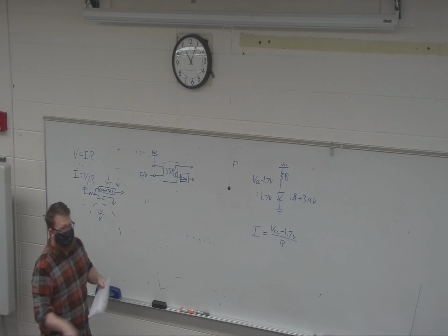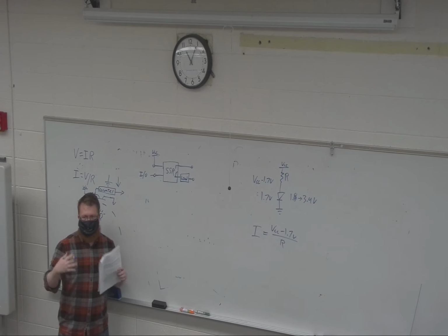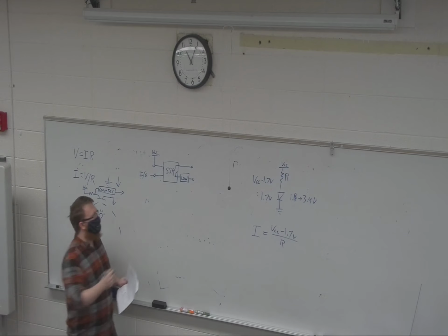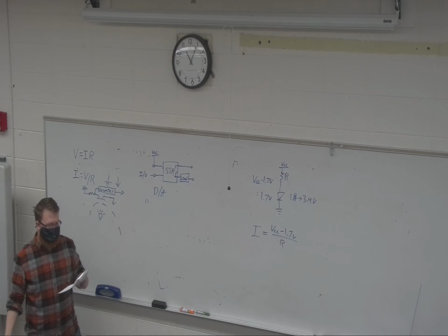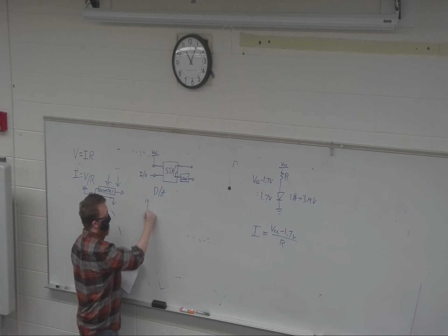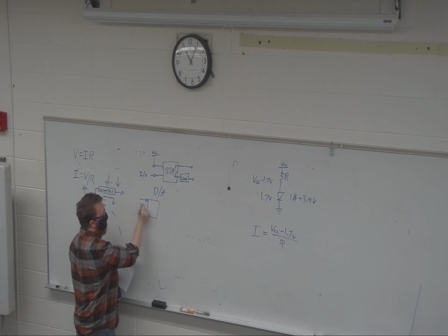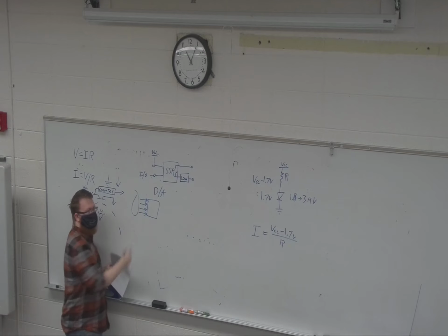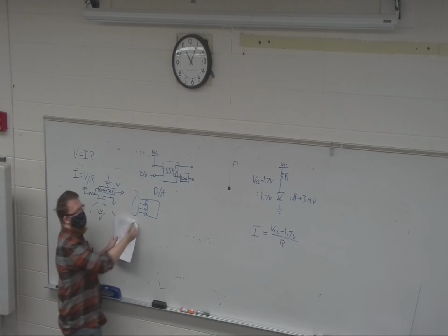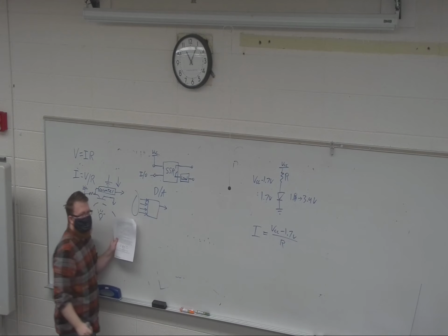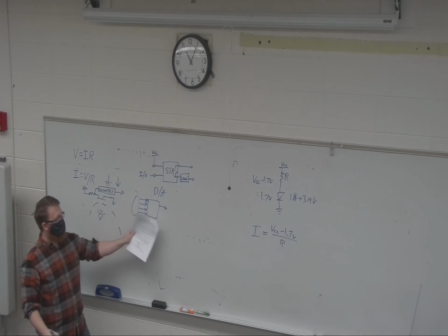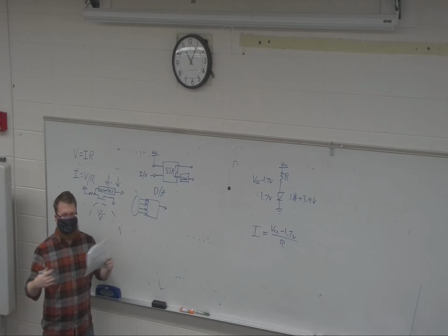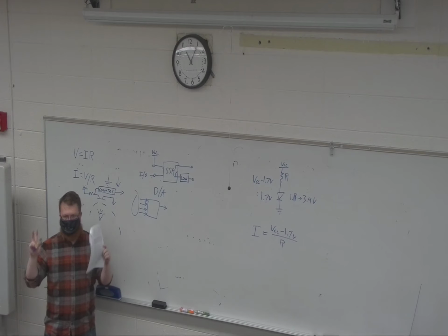Another important device is, we've talked about inputs, now we need to get data out of the system. These are called D2As, digital to analog converters. Again, we're going to draw a box, because we always draw a box. It's going to be a nice 4-bit, with 4 digital inputs, and it's going to output some analog voltage. So it has numbers here, which is compatible with your digital system, and it outputs analog voltage. That's how you go from digital system to real world.